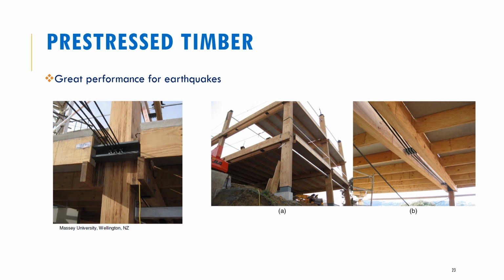Now, when we talk about structural timber, of course, there's another application of structural timber, and that is pre-stressed timber. This is when you have these tendons that are attached to your timber structure, and they're tensioned in a way such that it allows you to withstand greater loads for larger spans. Okay, so you can form bigger spans,